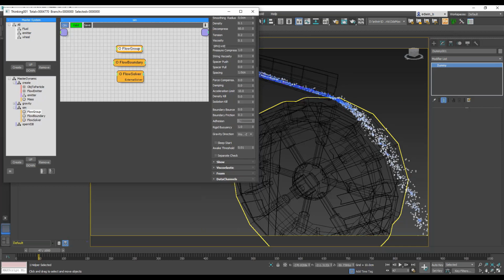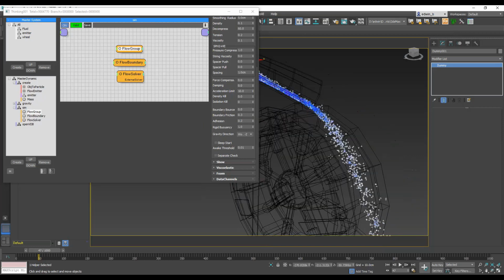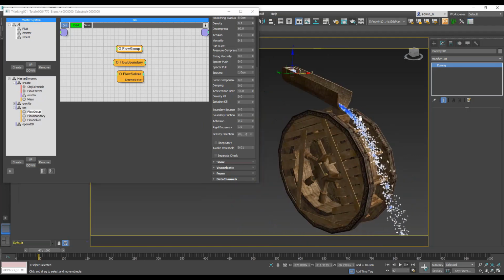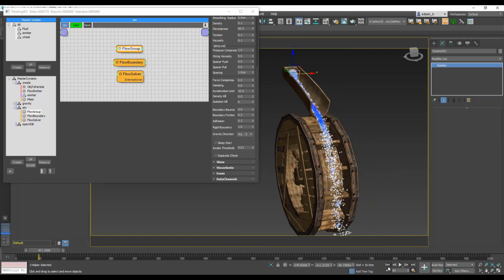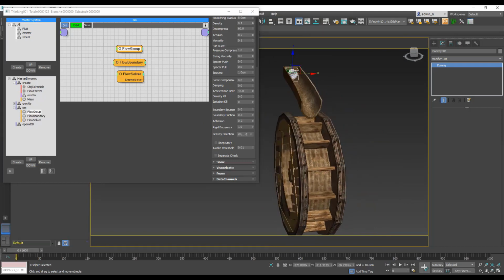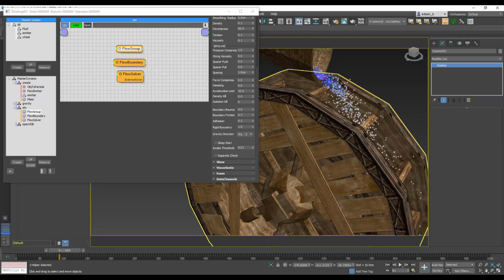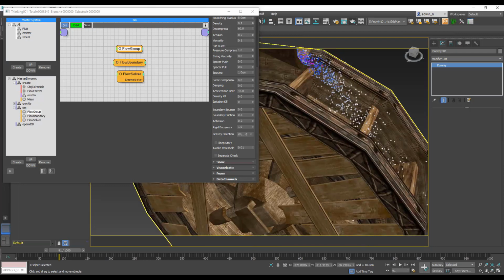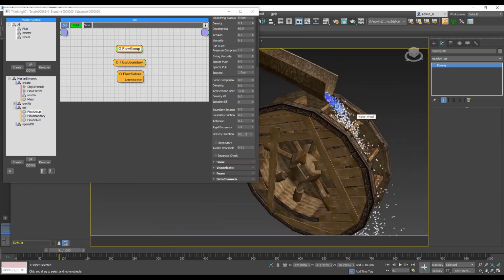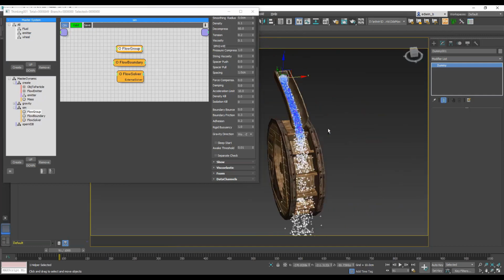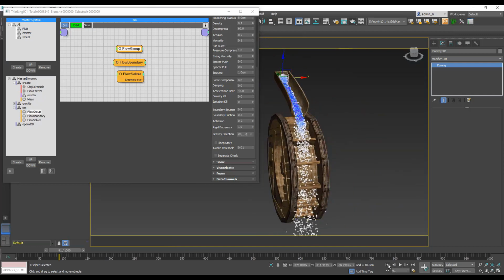And also adhesion is an effect that we always see with fluids. I'm just guessing here with parameters. Let's just dial in a little bit of friction and adhesion. And now if we simulate again, we should see a different behavior of our fluid. And you can see now our fluid is tighter, much, much tighter. And we can see we also start to hit now our container here. So we are getting to a point where it actually works.